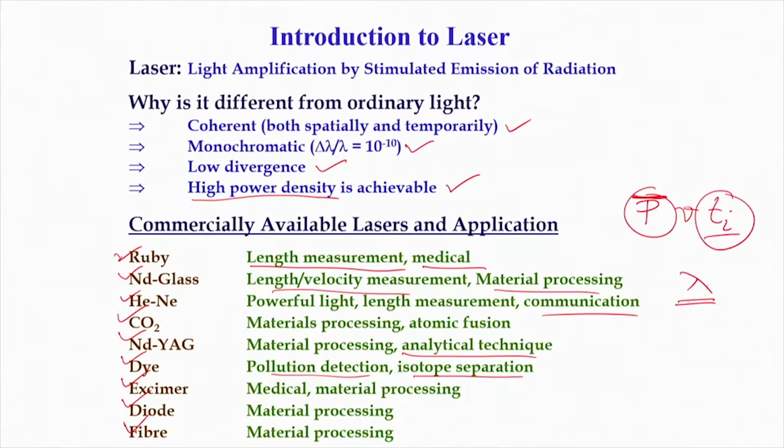Then in addition to this, these are from the laser side. From the material that is going to get processed, there are two or three things which are very important. So overall, one is the laser related parameters, and there the power density, the interaction time, wavelength, and various other laser related parameters would be important.